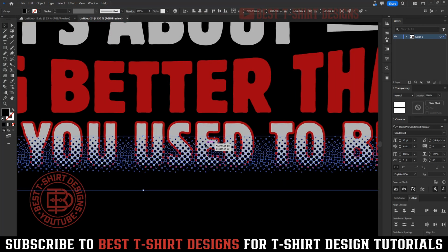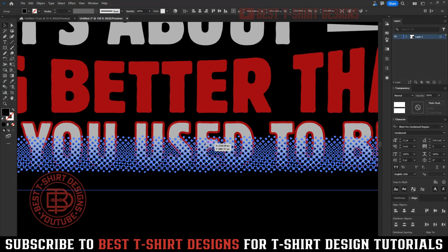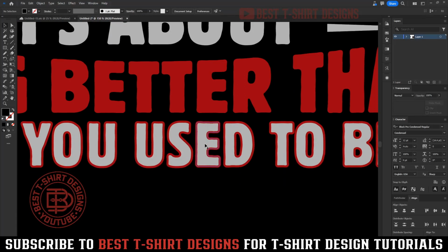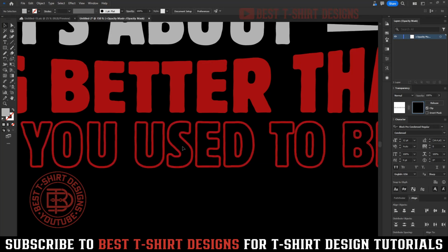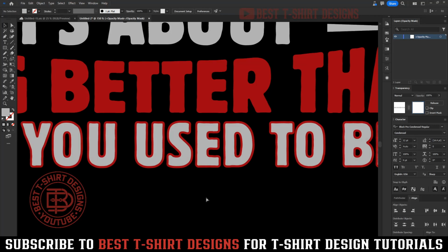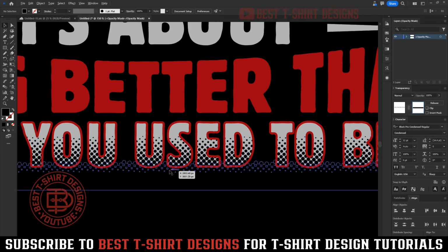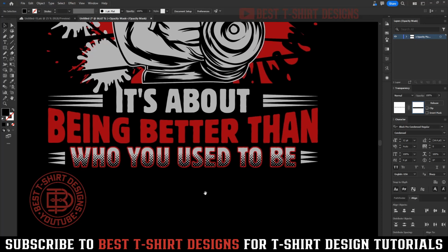So I'm going to select this silhouette now. I'm going to cut it. I'm going to select this one, the inside fill shape, and open Transparency. As you can see, this is not being selected, and then here I'm going to press Ctrl F. So Ctrl F will place the texture here, and as you can see, this is how it is looking. So that is fine.